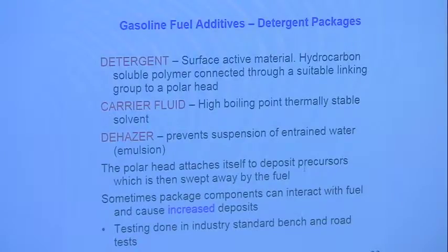But this is the thing. Sometimes these package components can interact with the fuel and cause increased deposits somewhere else. And this was, by the way, a big issue when port fuel injection engines were introduced about 25 years ago, because they found that there were problems with injector plugging, and so they put detergent additives in them. And what were the detergent additives at that time?